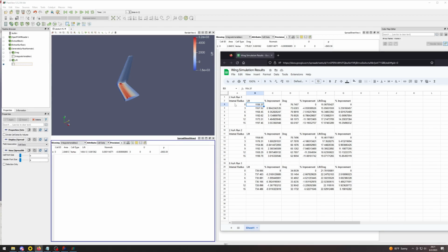Normally a 1-degree increase in angle of attack would significantly decrease the speed because the plane would be slowing down. And we can see that there's a huge increase in drag when we try to maintain that angle of attack at this speed. That would be like pulling back on the controls. Maybe pulling a few Gs, probably not quite 2, but maybe 1.5 or something like that.